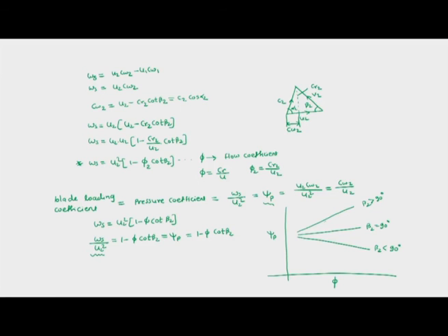And then this gives us a hint that this is an unstable design, and that is why this would not be preferred. But these designs corresponding to radial and backward facing vanes are stable, since psi p is decreasing with respect to phi, so these designs will be preferred.